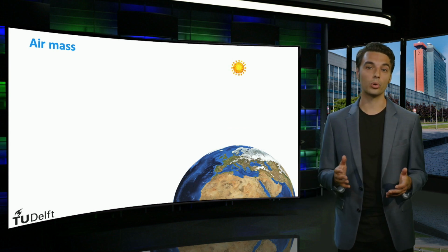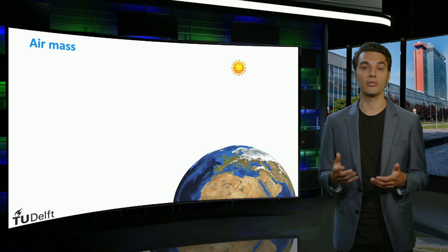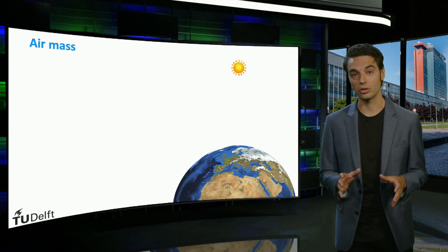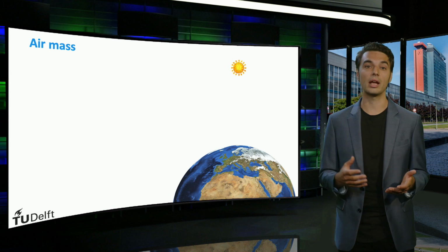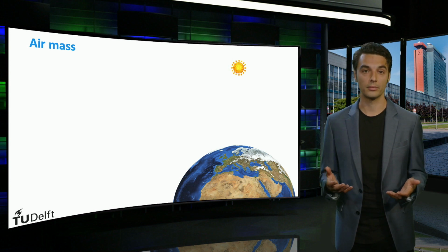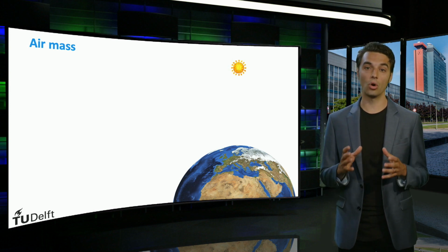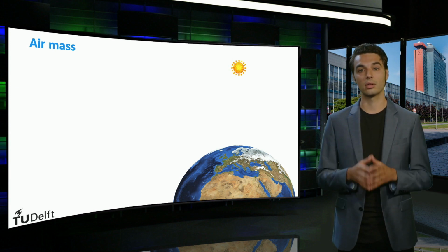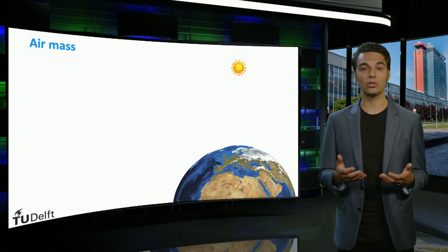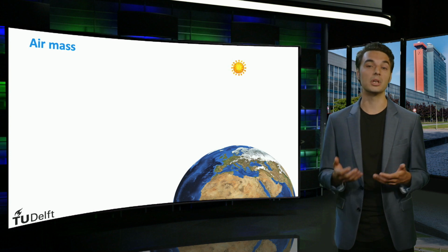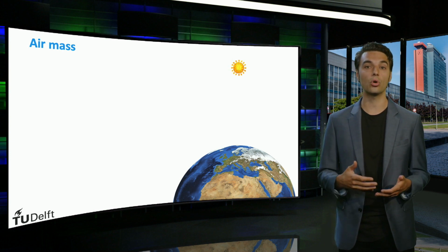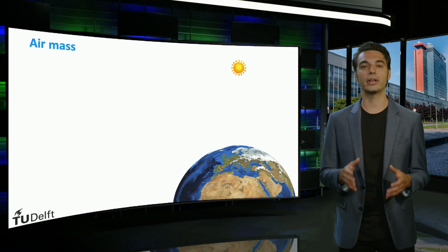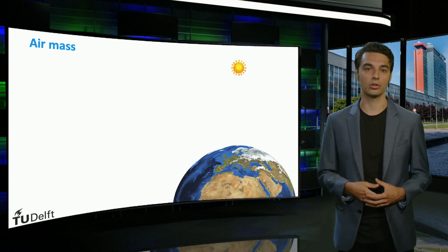The most important parameter that determines the solar radiance under clear sky conditions is the distance that the sunlight has to travel through the atmosphere. This distance is shortest when the Sun is at the zenith, so directly overhead. The ratio of an actual path length of the sunlight to this minimal distance is known as the optical air mass. The figure shows the Sun at its zenith position.